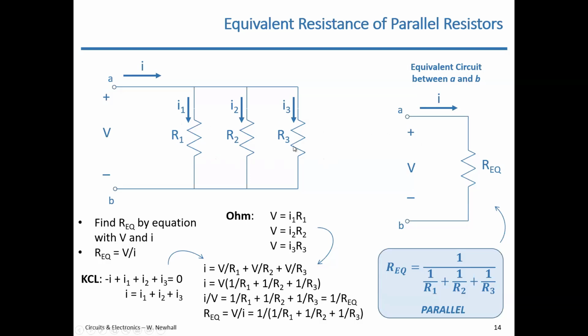So when you combine resistances in parallel, having these more lanes, you can get more traffic, so the resistance actually drops. If you take three resistors and each has some value, the parallel equivalent of those resistors is always going to be smaller than the smallest resistance. So you could add a fat lane, a skinny lane, and a skinny lane, and the overall traffic you could get through is greater than the widest lane.